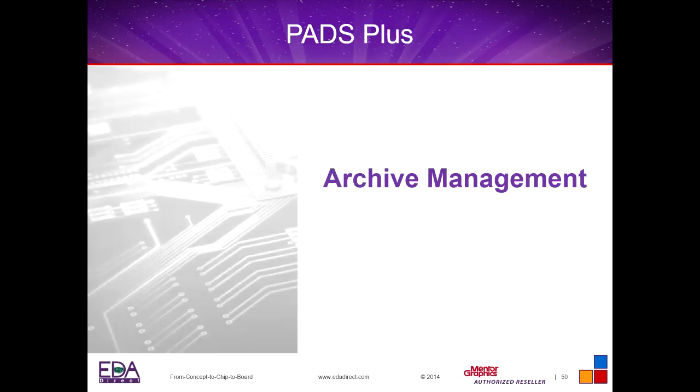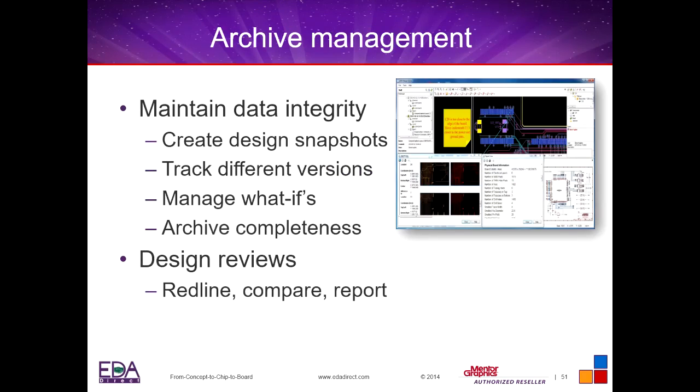Also added is an archive management tool. With this tool, you'll be able to archive the data that you've generated. For example, your Rev A's and Rev B's and Rev C's, we can archive those right into the archive management tool, and it's going to allow us to create snapshots. So an engineer can now come into this tool and, for example, want to see the differences between Rev A and Rev B. He can do that by calling up the schematic of the board, running a graphical compare, and it'll give him a list of what the differences were.